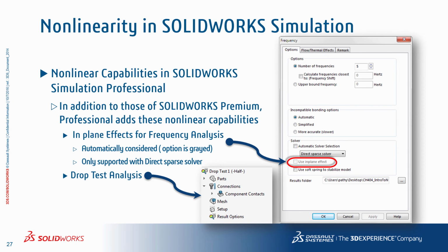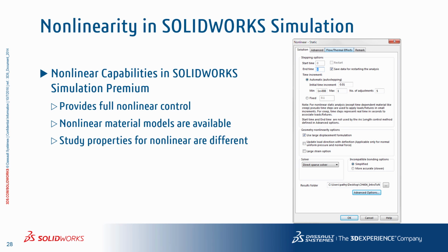And finally, in SOLIDWORKS Simulation Premium, there are two additional tools available. One is providing full control over the nonlinear solver, and secondly, allowing to simulate exact material responses using various material models. A nonlinear material model allows you to input stress strain data for metals, plastics, elastomers, nitinol, and so on.